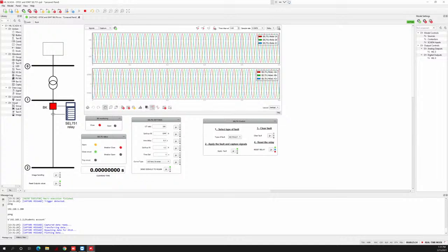In this case, she is using the time dial number 1. And if you look over here, there are different types of dials. I think this is number 1. And this is the multiplier that she is using for the pickup current. What I'm trying to say is if there is a short circuit, that short circuit current will go here and intercept, and then you will have the time. This is the kind of curve that I'm talking about, the inverse time curve.